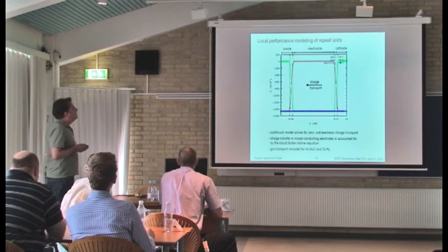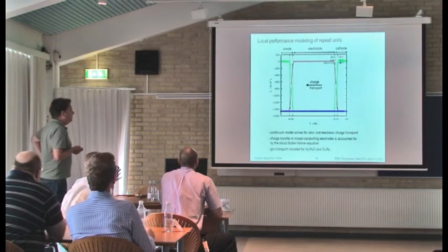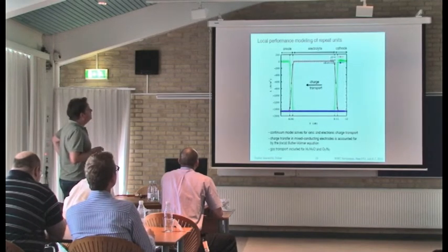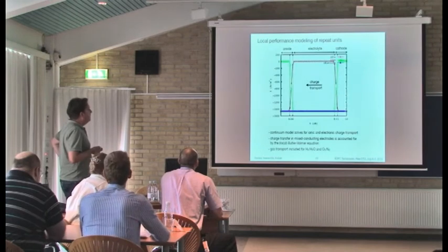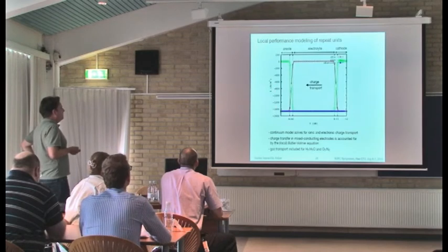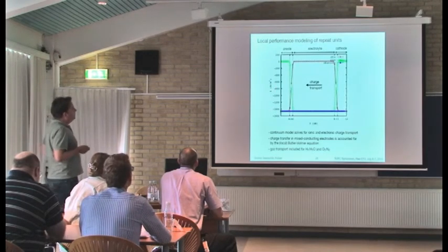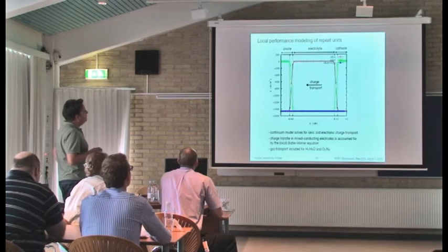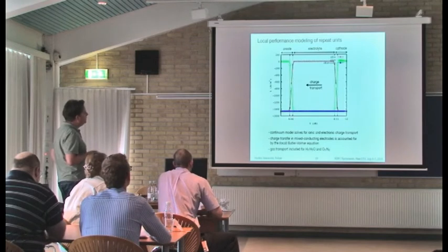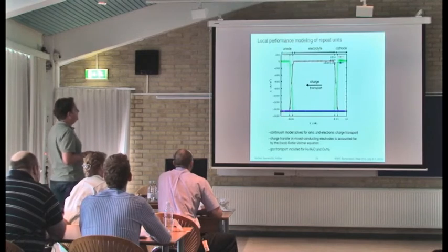Okay. So here you see some results from this full cell model. In red, this is the electric current. It's a bit cumbersome because those are negative values. You see that within the electrolyte you have no electronic conductivity, and then it increases here. This is the anode side, then you have two different anodes, let's say a catalyst layer, anode 1, and a current connection layer, anode 2.